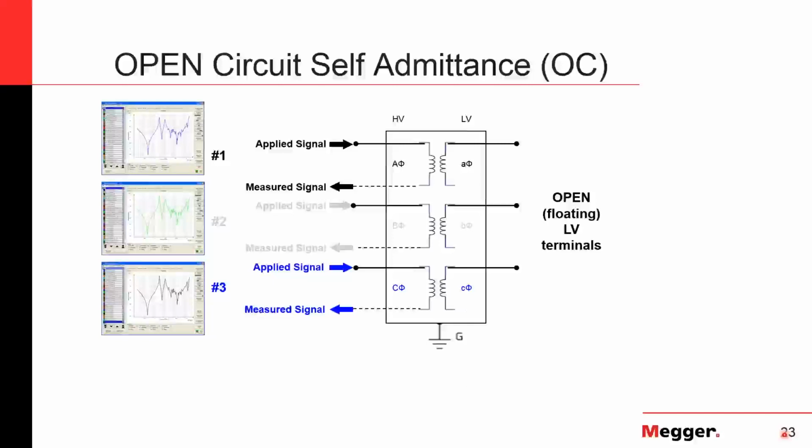So now there are four types of tests. But the difference here compared to some of the other ones, like in power factor, where you just do one overall bulk insulation test, is that here you're actually doing everything by each winding.